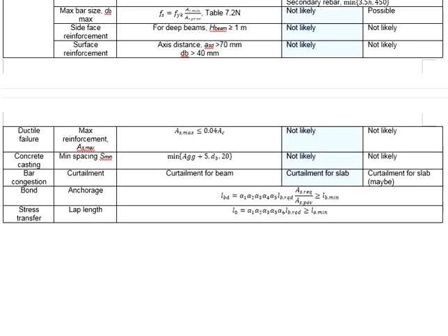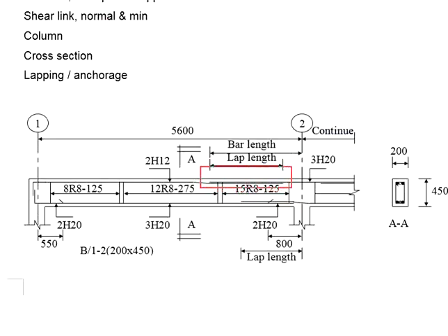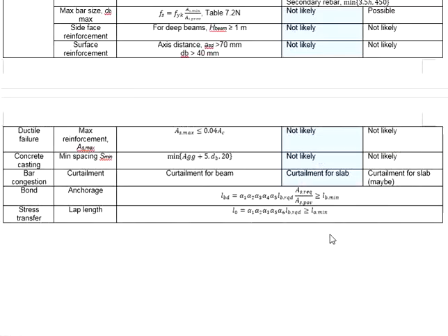You can choose to reduce the amount of reinforcement bar provided. Since the extra is not necessary, that will lead to two sizes of reinforcement bar meeting. This is when you need the lapping length. The size changes and you will need a certain lapping length so that the stress can be transferred effectively from one bar to another. The formulas to calculate the lapping length are given here. You can obtain these from Eurocode as well.